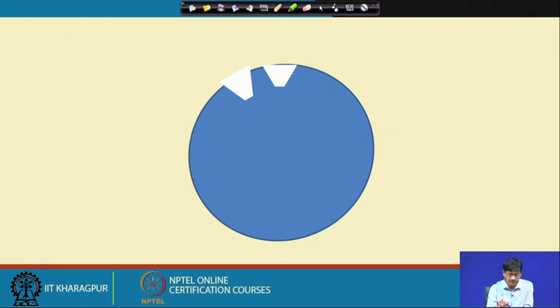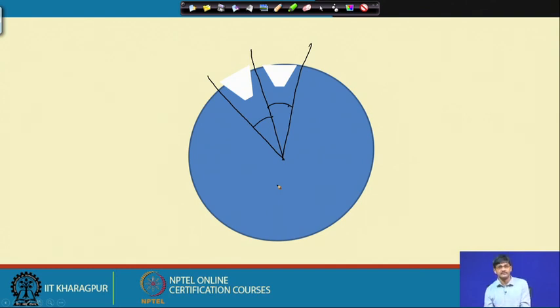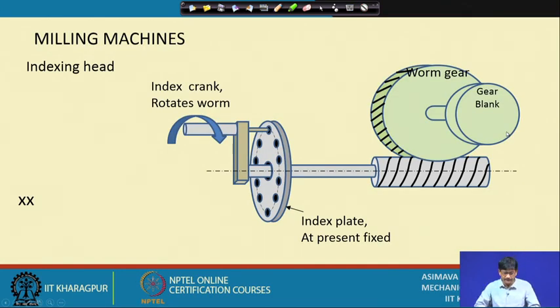So, we have to make it possible to rotate by this amount every time. Every time I cut a tooth, if there are 71 teeth here, 1/71, 1/71, this rotation has to be given successively 71 times. Okay. So, now that we have understood what is to be done, let us see how it is done. So, we had started from here. So, let us move on forward once again. This body has to rotate now in order to make up rotations which are 1/71.